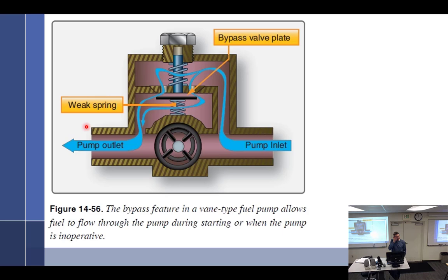That can be good, that can be bad. So the Continental fuel injection system uses a pump. I don't want to get too far ahead of us, but the whole system is based upon how fast the engine is running, and it's calibrated to that. So if you override the fuel pump, then you've overridden the brains of the operation. So in a Continental, you can actually overboost the pump and flood the engine. So that's a problem. You got to be careful with that. But with the Lycoming system, you give it all the fuel you want, it'll deal with it. You'll see through the diaphragms and stuff.